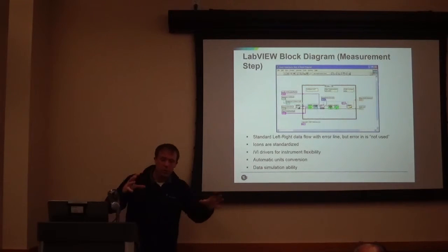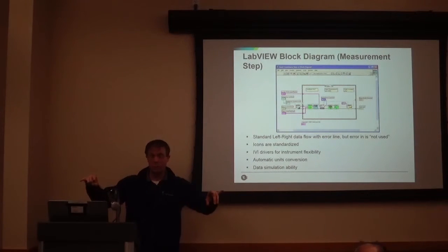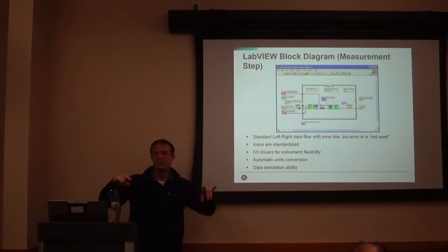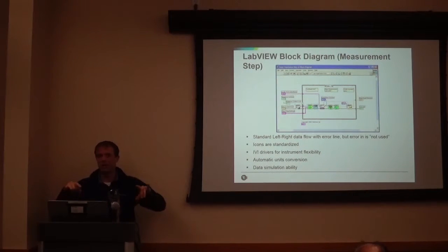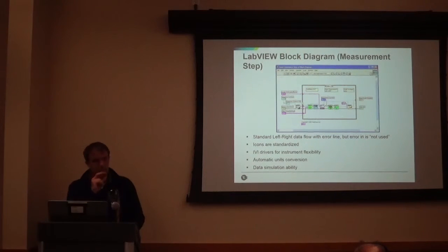Right. TestStand has the ability to do parallel testing, so I can launch multiple instances of this in parallel. But trying to get parallel testing working well is hard. TestStand has its own language. You can script it and talk to the instruments itself, but for a step it can also call a VI, call a .NET program snippet, or whatever. So that is a recommended one.